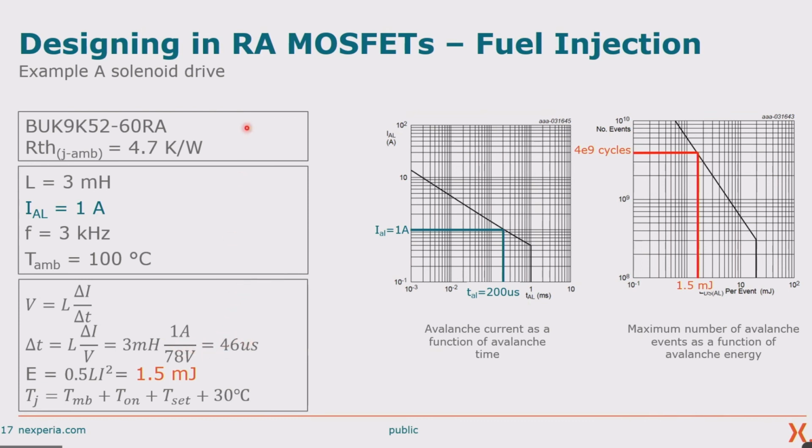This is an assumption. It's better to measure the MOSFET avalanching voltage. Yeah, that's the typical breakdown voltage of our trench MOSFETs, about 30% higher than the VDS rating of the product. So that's just the nature of how we create the devices. So that's kind of where that comes from.